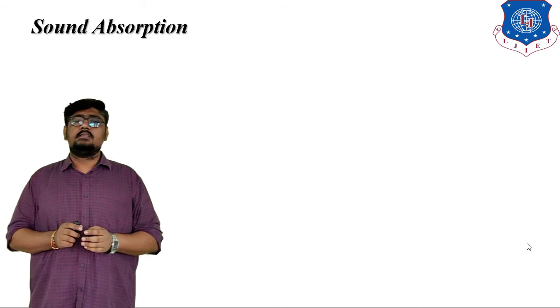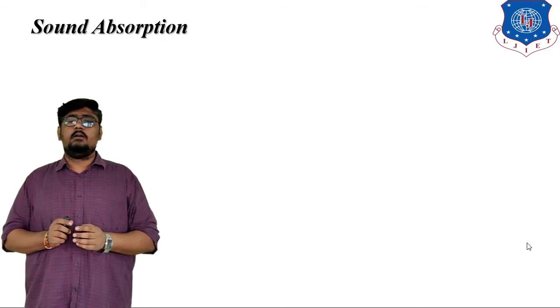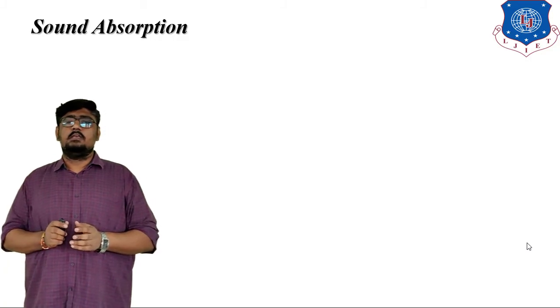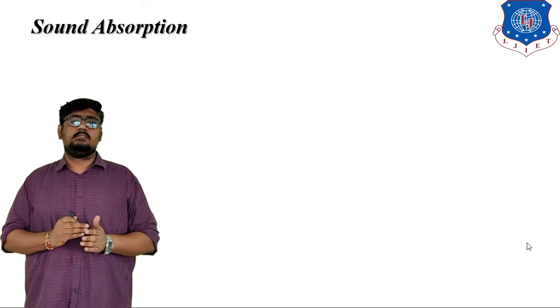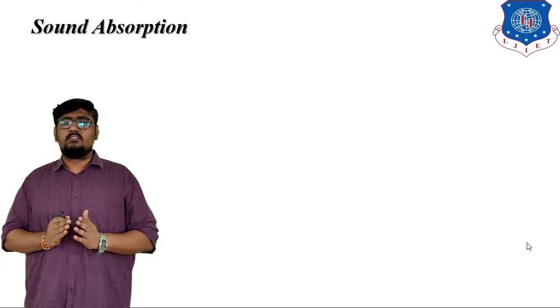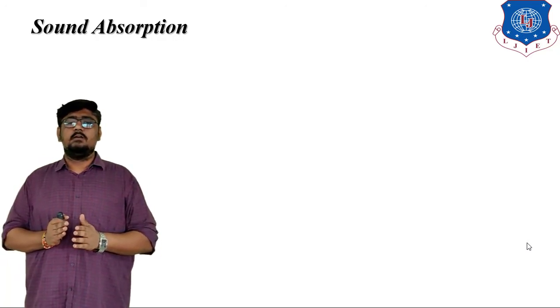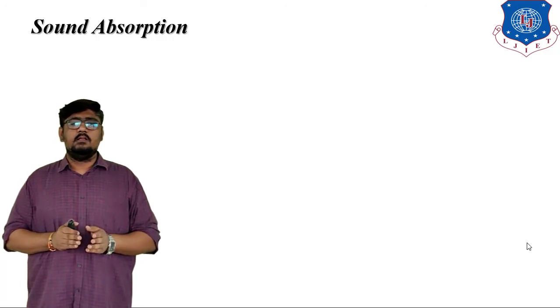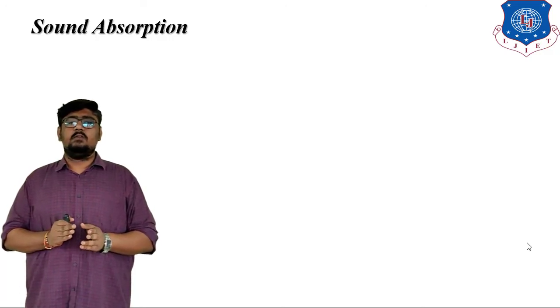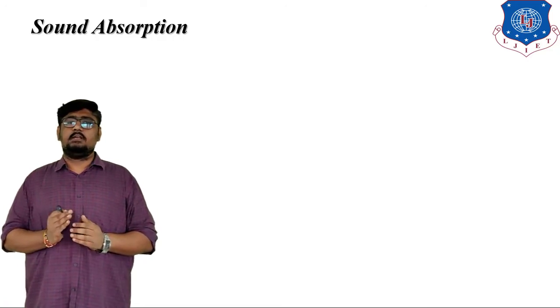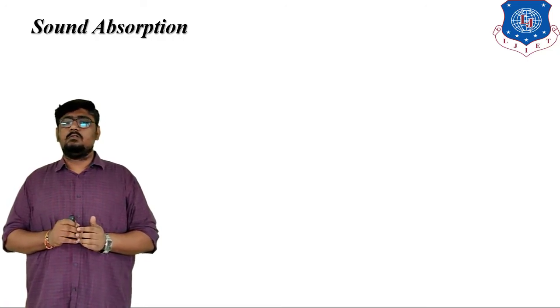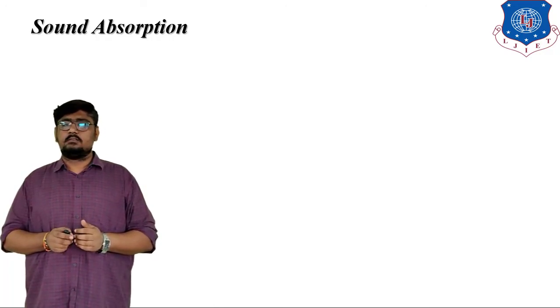The listener in such a room will have a problem registering the speaker because he hears both direct sound and the repeated reflected sound waves. If the surfaces instead are covered with a sound absorbing material, the reflected sound will decrease much quicker and the listener will only hear the direct sound. Also, the general sound level in the room will be decreased.